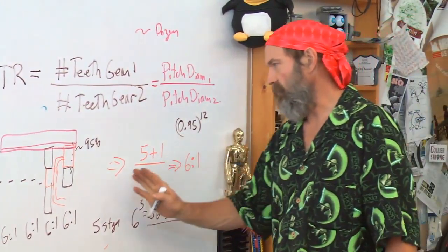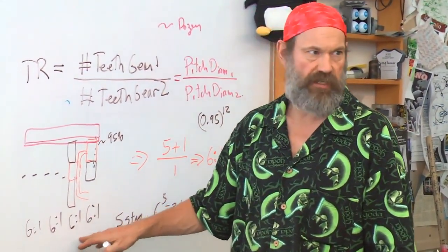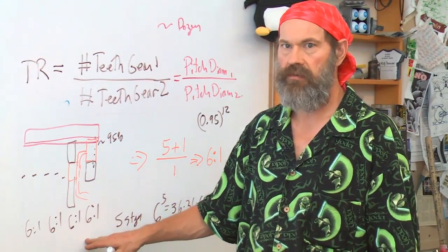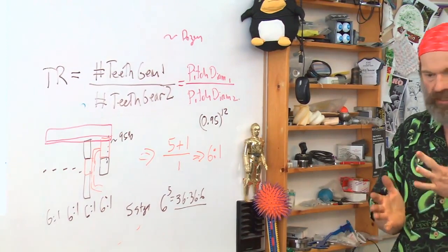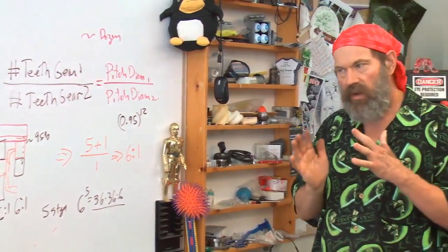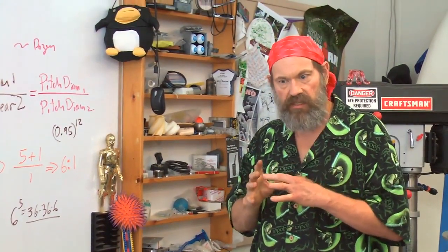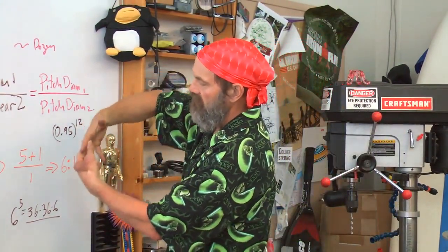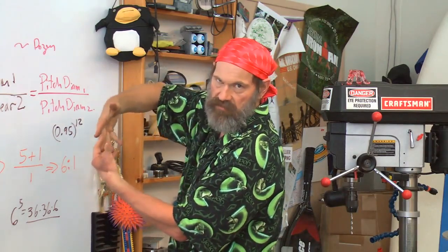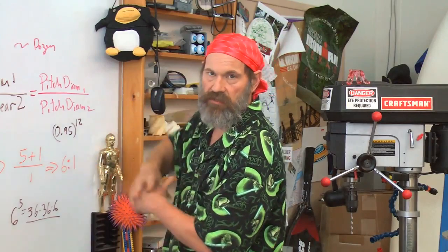So you may end up with a very high gear ratio, but you may end up with 50 or 60% efficiency at most. So it depends upon how precisely you've made your gears, how well you've designed them, what are the bearing supports to keep things perfectly concentric such that the teeth mesh really well and they're not doing all this kind of trash motion as they're moving, because that'll all cause a lot of loss of efficiency.